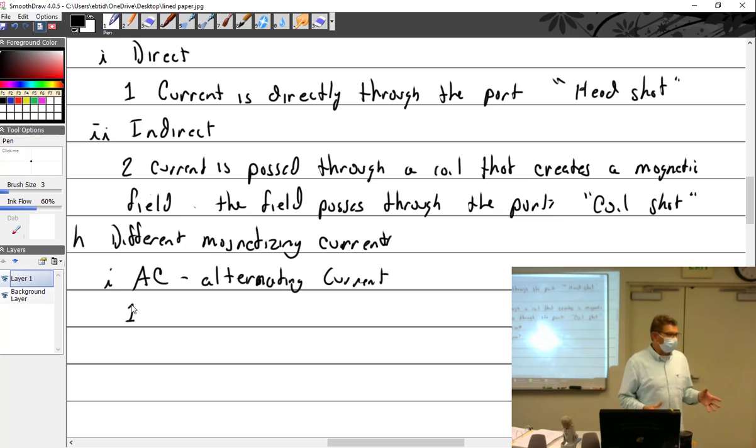All right, so the theory is, if you're a manufacturer of steel parts, what kind of defect would you expect from a brand new part? Why subsurface? Inclusions in the forging process. Yeah, inclusions in the forging process. These are gas pockets, or that's one of the bad things about the level 3s. You get to learn all of the different, a gas pocket, a pipe, a cold shut. There's a million little names for these things, but we'll just call them discontinuities,